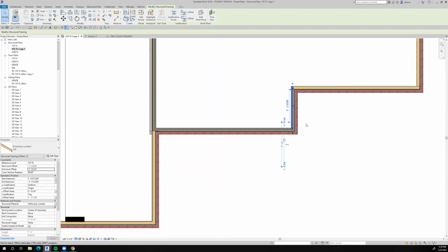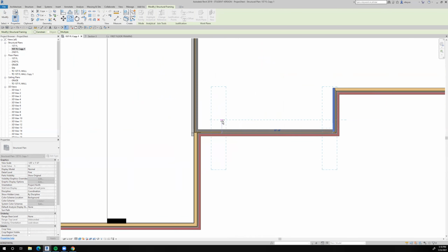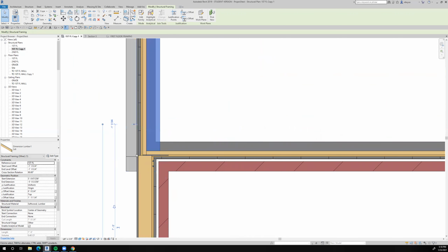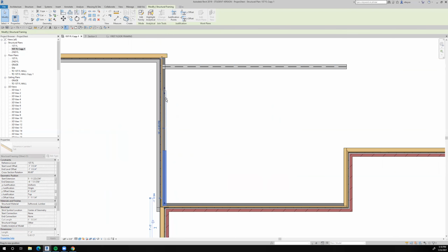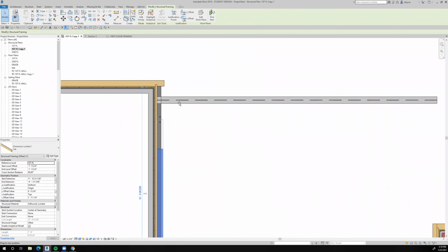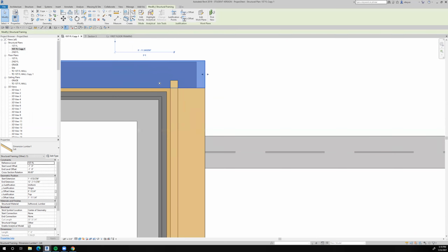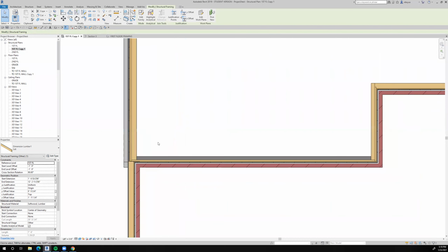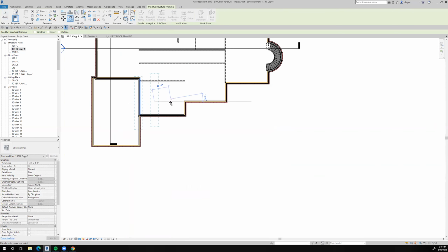So you'd also have to make a note for the concrete basement guy to make sure that they drop the top of the basement wall 3/4 of an inch, or this won't work. In other words, you won't be able to drop this down 3/4 of an inch if the basement wall is the same height as it is all the way around. That's a mistake you would only make once in the real world, because it would be a lot of effort to chip out 3/4 of an inch of that concrete. In fact, probably what they would do if that was a mistake is put a 3/4 inch thick material up here for the sill plate instead of a 2x6. But it's better to drop it down to begin with.